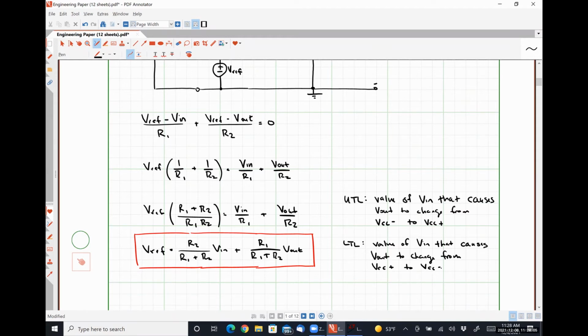Cheston: I noticed that this looks like voltage division, so how come you wouldn't use V out to do R2? That you wouldn't flip V in and V out? Because we're figuring out V in because we know how V out is going to behave. It's either going to be VCC plus or VCC minus. Now we do have ratios of resistances here that look voltage division-ish, but that's not really what we're doing here, okay?